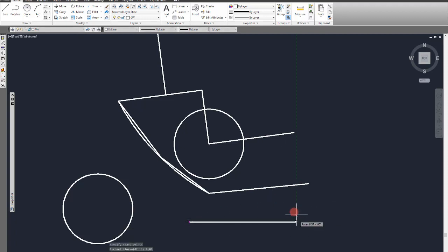Polyline. For arc, you press A and you have your arc. For circle, just C and you have your circle. And it's very specific for Autocad that all commands can be either selected from the menu or, which is most often used, just typed, and you can build your own shortcuts. But generally you need to learn that for line you have line and PL for Polyline and so on.